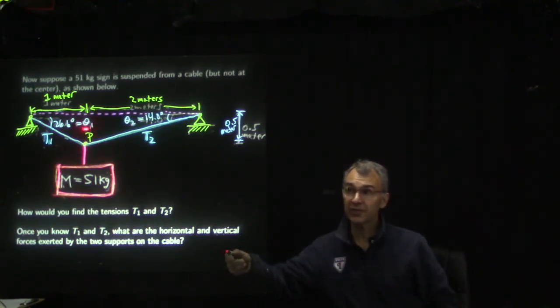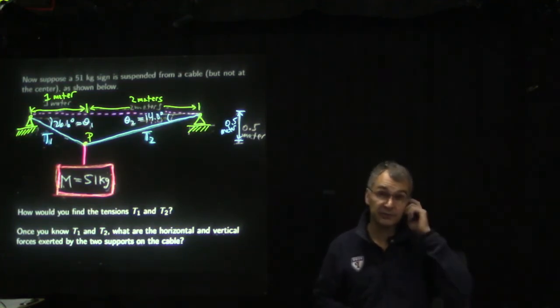No, it actually turns out there is no torque equation we can write for point P because all 3 forces have lines of action that pass through the point P. All these forces pass through this same point, so there's no torque equation we can write. But we can write a horizontal force equation, and a vertical force equation, and we only have 2 unknowns. Good thing we only have 2 unknowns, because we only have 2 equations to find them.